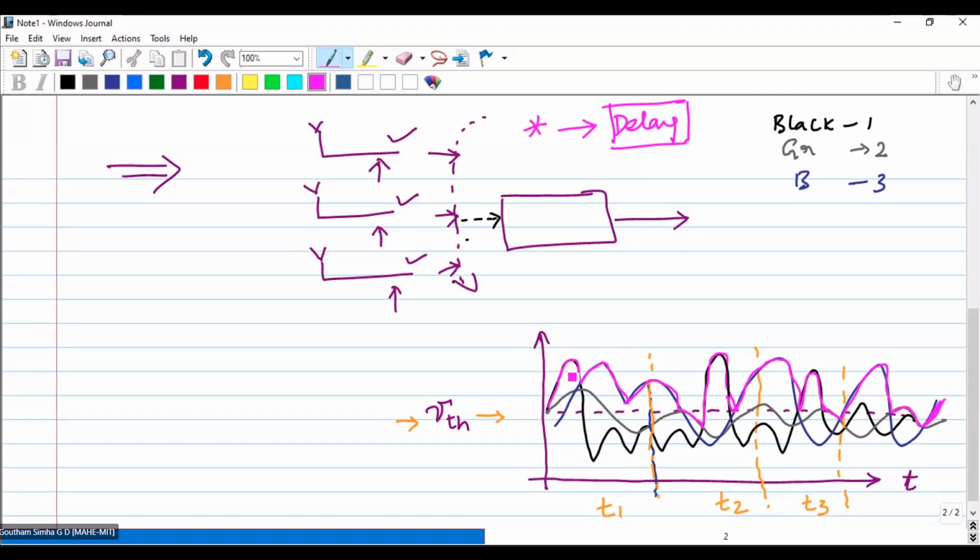Now look at this. Now what is happening here? The peaks have been reinforced. The peaks have been followed. The level crossing rates at the threshold SNR has changed. Now if you follow the black one, what happens? The SNR will go below the threshold level.